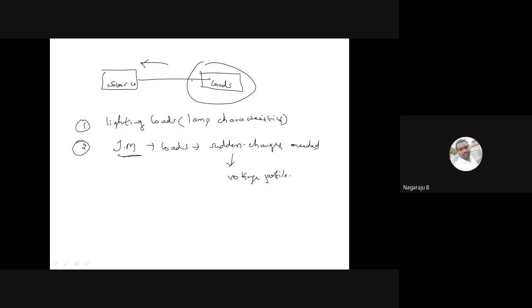If the supply voltage is more than the normal condition, the motor may operate with a saturated magnetic circuit, and consequently a large magnetizing current will be drawn.